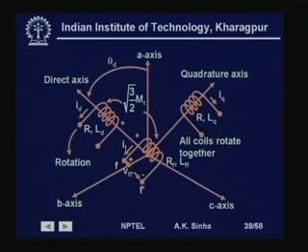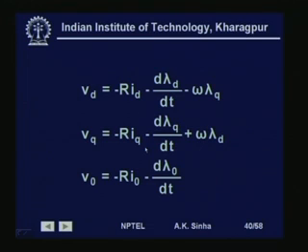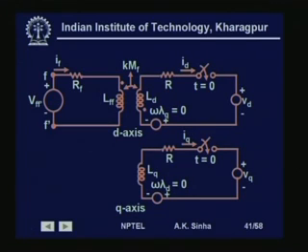As I said, there is the rotor, the direct axis and the quadrature axis, and this keeps rotating at the same speed along with the rotor. Then we write all the relations for voltage and flux linkages in terms of the dq0 frame of reference, and we avoid the time varying inductances in this case. So, this is what we get.